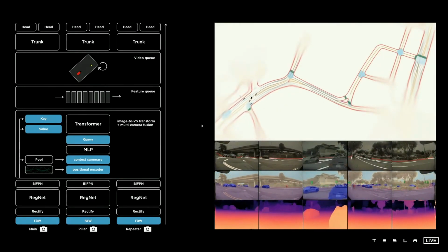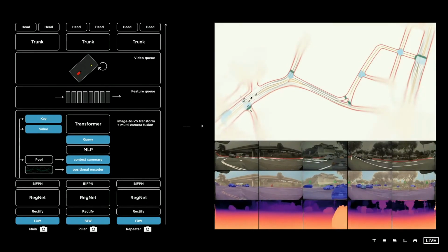Or for example, our outputs are dense rasters, and it's actually pretty expensive to post-process some of these dense rasters in the car. And of course, we are under very strict latency requirements, so this is not ideal. We are looking into all kinds of ways of predicting just the sparse structure of the road, maybe point by point, or in some other fashion that doesn't require expensive post-processing. But this basically is how you achieve a very nice vector space.